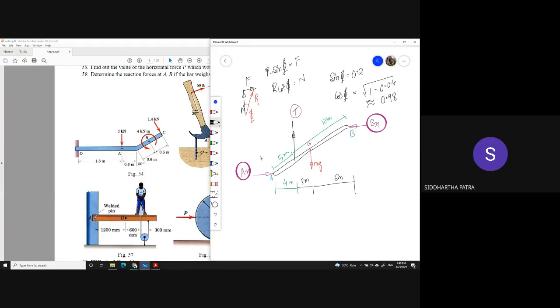The point is, for a low coefficient of friction, the normal force and the resultant force are essentially of the same magnitude. So using all that understanding, I would simply neglect the frictional support because I don't have enough equations. Now for this geometry, let's call this point C. Try to get the free body diagram.